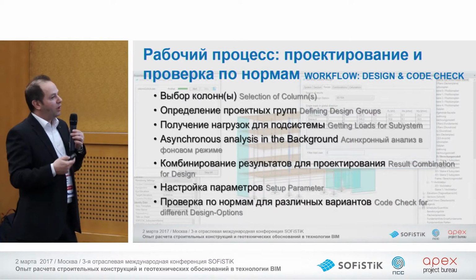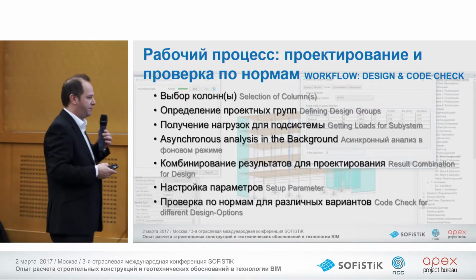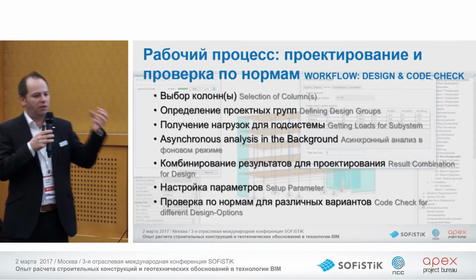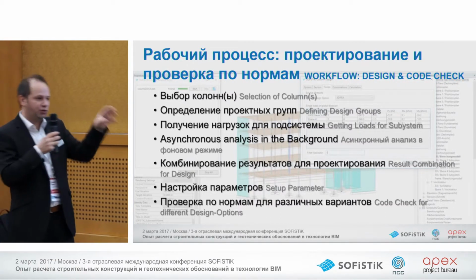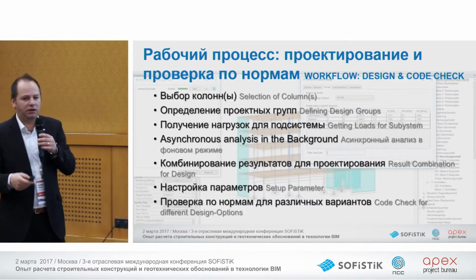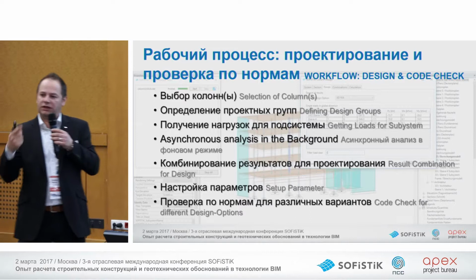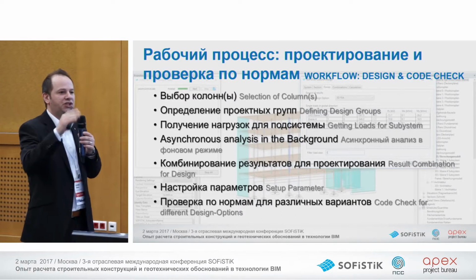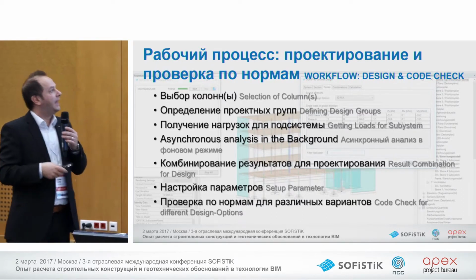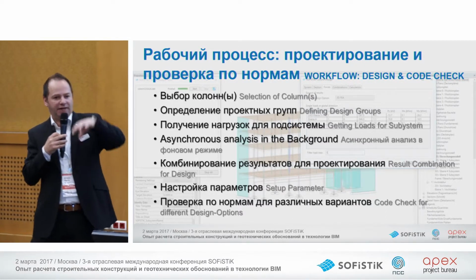what's our workflow? The workflow is that we have a model getting from Revit. We can drive all the analysis, as Stefan has mentioned, like 3D, 2D, 4D. We would like to give the possibility also to have a completely new possibility to understand your building, combining 2D and 3D, get out some subsystems automatically, and maybe we like to do that directly in Revit, that you can, for example, select a column in Revit, do right-click, defining some groups for that column, so means select columns which are quite the same, which have the same geometry, quite the same loading, quite the same system. And then you can apply some group information to do a design for these sub-elements, okay? And then you can get an envelope of all that data.